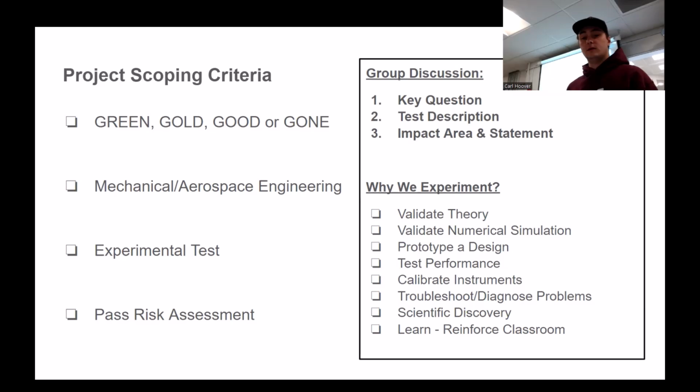So my test plan, they would have some sort of braking apparatus where the RPM and braking force would be constant and set, and we can measure the time it takes to stop the rotor, and the heat. There would be a series of rotors, and each one would have a different amount of drilled holes. You could do that in a uniform pattern or test different patterns and see how that works, and come up with some sort of ratio or range where it is optimal.